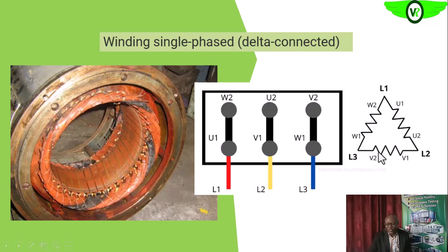So you are feeding just one set of winding. It is entering and returning, entering and returning, through just a single winding in the system. So that sustained overheat, as we explained earlier, will cause the burning of this V winding. That will show up as just a 1/3 section of the winding being burnt on the electric motor itself. So this pattern shows us clearly that the problem we had was single phasing.